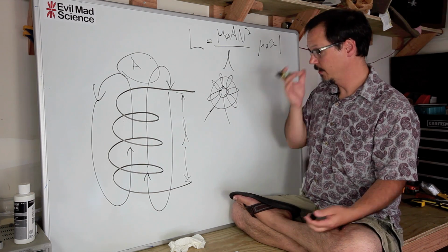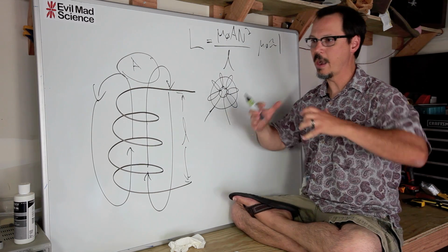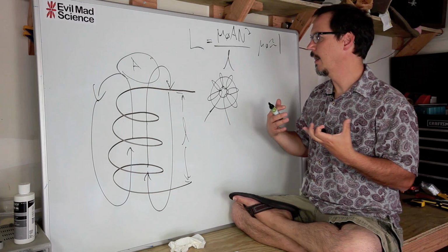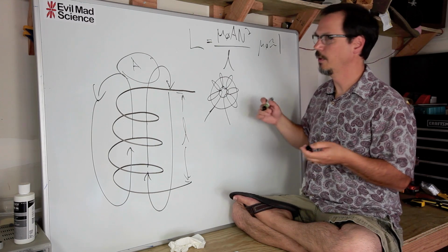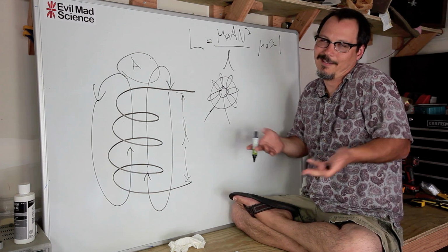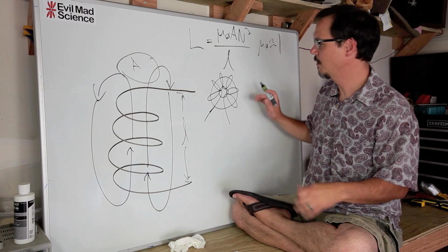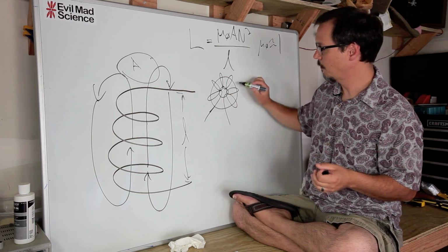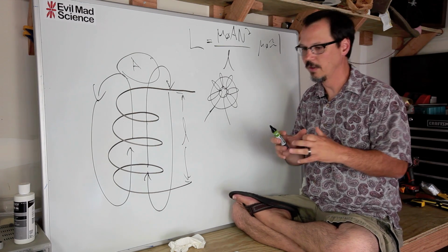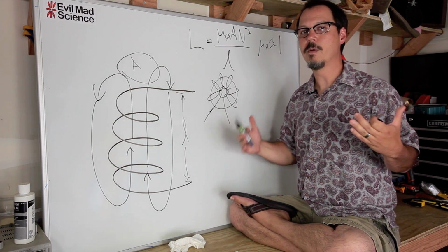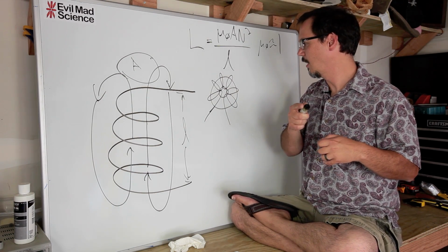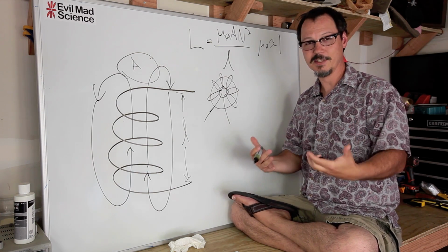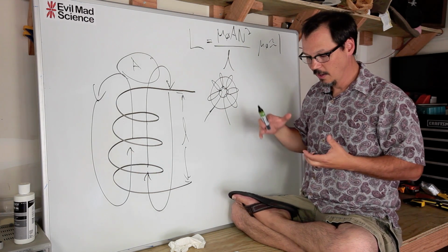So a lot of times they will put a can around the inductor, and the can is made of a magnetic material, a ferromagnetic material like iron. I'm sure they don't use iron, but they use a material that focuses magnetic flux, because, as I said, the flux will tend to stay in the material that is more permeable. It will not go out. I'll show you this. I have to go find it, but I've got a transformer that's got a can on it, and it's pretty cool. The whole reason for that is so that it maintains the flux within it.